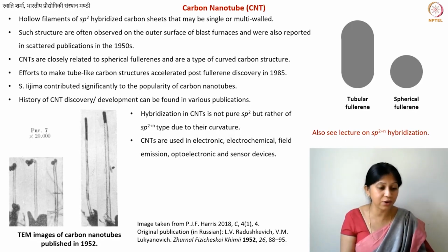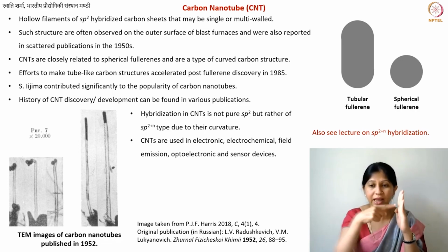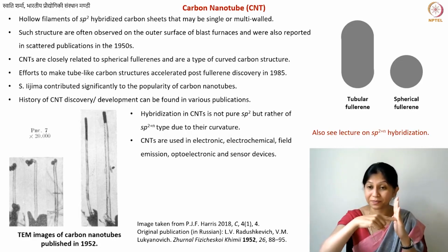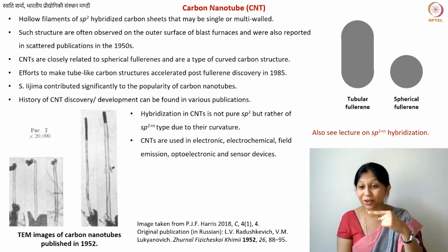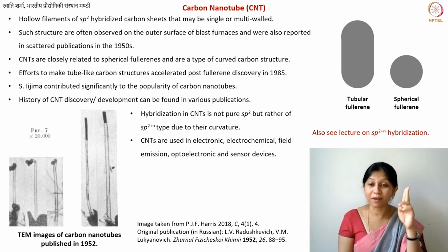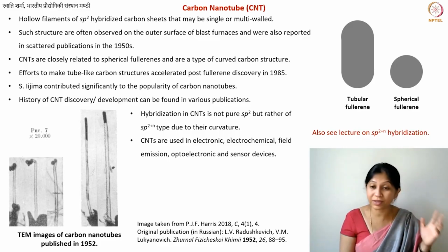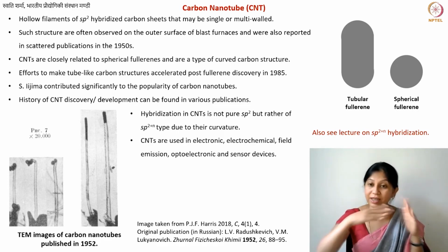So you learned that when you have a zigzag type carbon nanotube, when the face of your tube is zigzag type, the path that the electron needs to take, that is perpendicular to it, right? The path during the electrical conductivity. So for the zigzag type carbon nanotubes, you actually have an armchair type of path for the electron. And for the armchair type of carbon nanotube, you actually have a zigzag path where the electron can easily travel. So these type of carbon nanotubes are then pretty much always metallic. And the zigzag type, however, can be metallic as well as semiconductor. So zigzag type, when I say the path of the electron is armchair type.